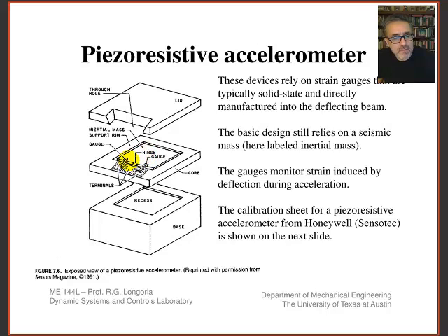You have a little stiffness built in with the MEMS structure. So you build a sort of strain gauge-like accelerometer, and these are very common. Think about how strain gauges are sensitive to constant forces. So these would also be good accelerometers for measuring constant acceleration.